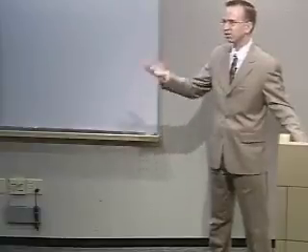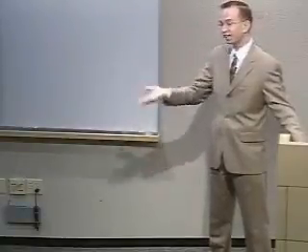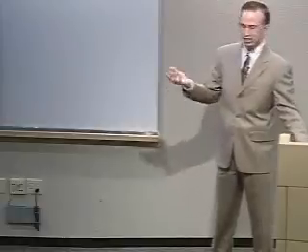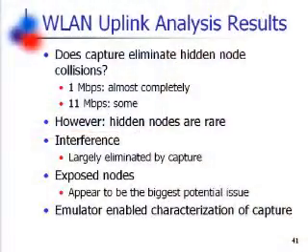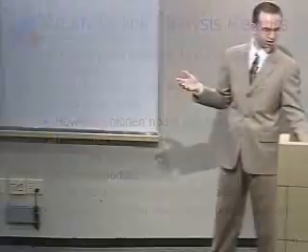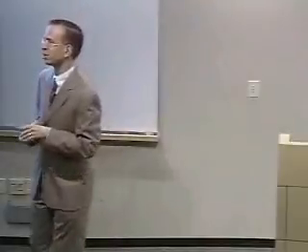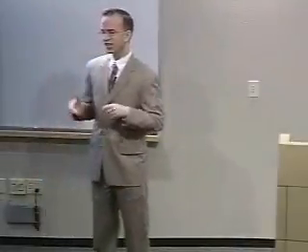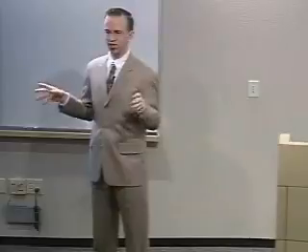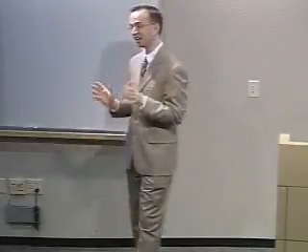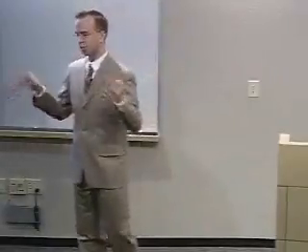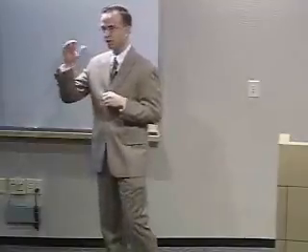Are there lots of hidden nodes? Are there lots of nodes that might collide with each other? So again, we didn't actually perform packet level simulation. We just looked at the signal strength between the nodes and said, yeah, these two nodes could be hidden, these two nodes could be exposed. And the high-level result, which I'll be happy to talk about in more detail offline, was first of all, does capture eliminate hidden node collisions, hidden terminal collisions? And at 1 megabit per second, our results say yes. If everybody in the network were to talk at 1 megabit per second, capture would trump hidden terminal.